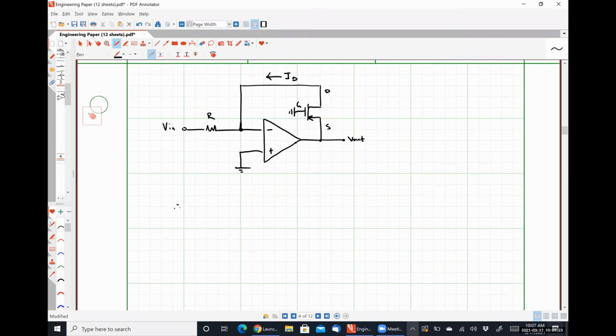So our output voltage relationship, Vout, not going to go through the derivation here because it's effectively the exact same operation, is going to be positive VTHP plus the square root of negative twice Vn divided by R mu P Cox W over L, where Vn has to be less than or equal to 0 volts.